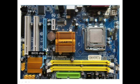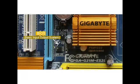So here comes the BIOS chip. BIOS stands for Basic Input Output System. In this motherboard they used two BIOS, dual BIOS. One we call M BIOS, main BIOS. The other one is B BIOS, backup BIOS. But normally in desktops they use only a single BIOS. Another name for BIOS is FWH. FWH stands for Firmware Hub. Since BIOS is neither completely hardware nor software, but software embedded into hardware, we call it firmware.